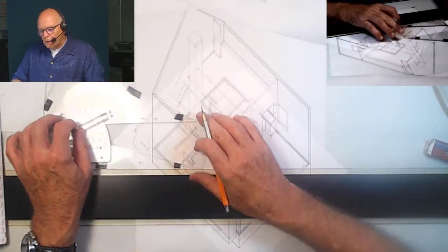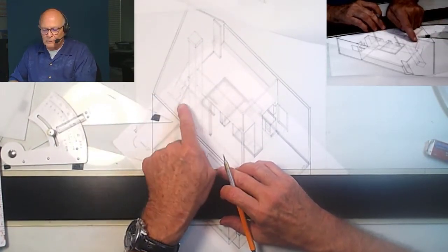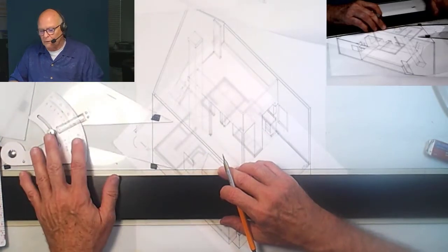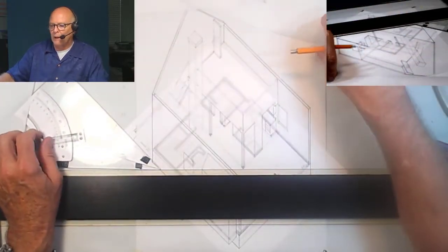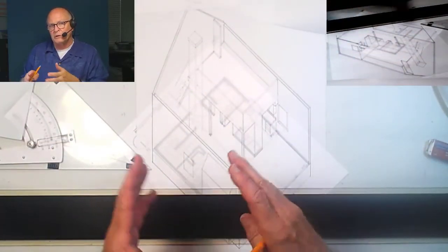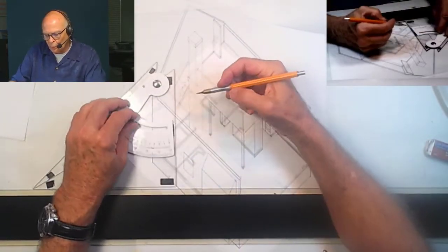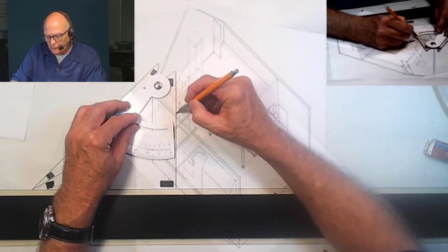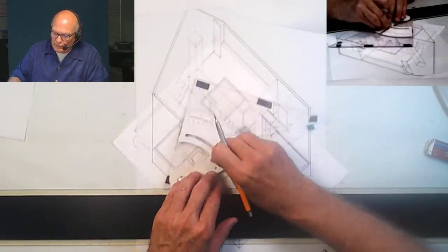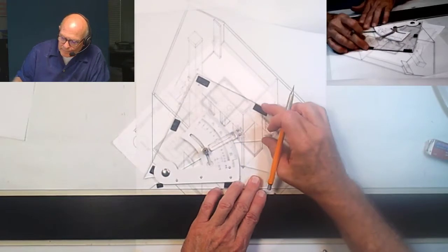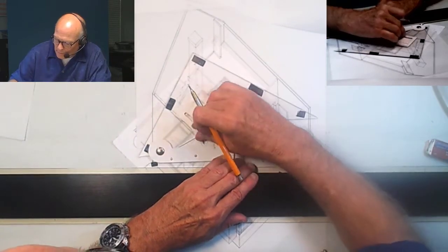Okay. So I've got my stair here. I don't have to really show it on this backside. We're not going to see it. But one of the things I do want to check is how far does this sloped wall actually go within the view orientation that we've got? Well, if you look down here, you can see this is where the wall ends. So I'm going to shoot a wall up at the corner here and another one at this corner. And I've got to get back to my slope here. Let's come back over here and make sure it's correct. Good. Adjust it.